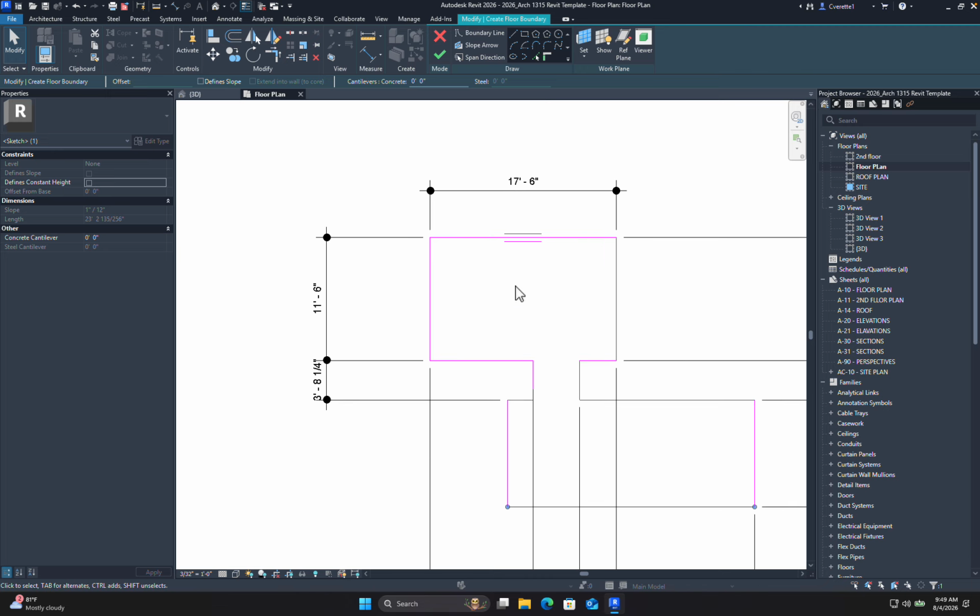But you'll notice, when in doubt, click on something, see if it has different properties, see if it has something that activates in at least a blue way. Now, by default, a lot of items are pinned, right? So you'll notice if I can't move something, it's because it's pinned. So I'll do pin to basically lock something. That's basically kind of like locking something in Revit. I don't type in lock, but I type in pin for pinning something. If I want to unpin something, I do up as in up, right? So if I do up, it unpins something, right?